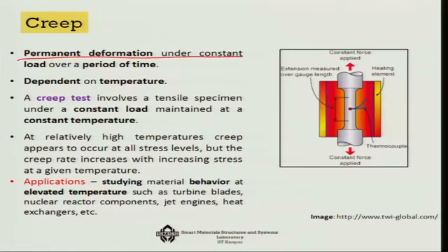For example, you use the nylon wear for outdoor garments drying, right, and you will see that you put a fixed tension, you fix your nylon wears, and then you put your garments day 1, and after a month or so you see that this whole thing is actually slacking, and it is coming down more and more, it is getting loose. So, why is this happening? This happens because under a continuous load, every material starts to get a permanent deformation over a period of time, which is known as creep.